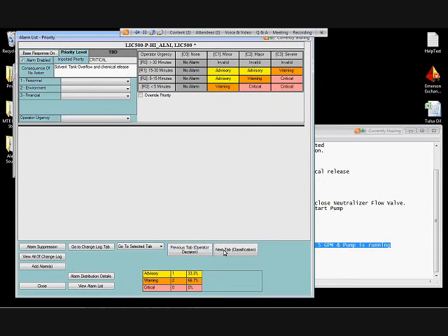So now let's look at prioritizing this alarm. We are going to assess the consequences in the area of personnel first. In the event that the alarm is not responded to and the tank overflows, there are people in the area at all times, so this could result in some injuries. So we'll do our assessment using these descriptions that essentially came from the alarm philosophy document, from the consequence matrix. Our experienced operators said they would expect that they would have about 5 to 15 minutes to respond.